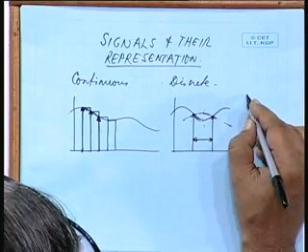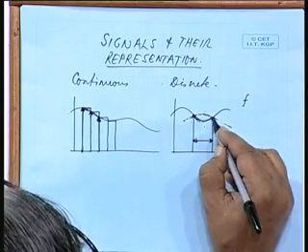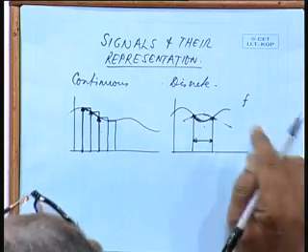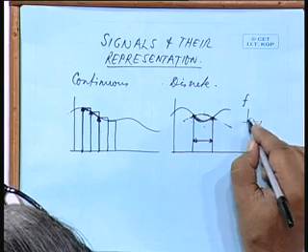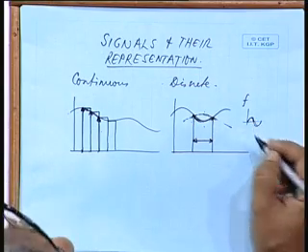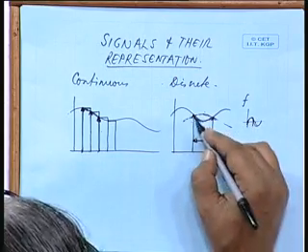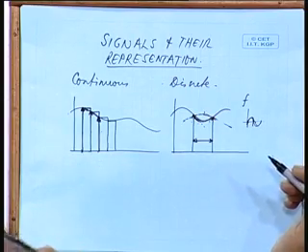is represented by some frequency, this represents half that variation. Suppose this can form at the most half of a cycle, half of a sinusoidal function. Okay. This is a maximum possible change, and if I take half that value, then I will be missing out the trough or the peak. So, the sampling frequency should be such that I do not miss out this.